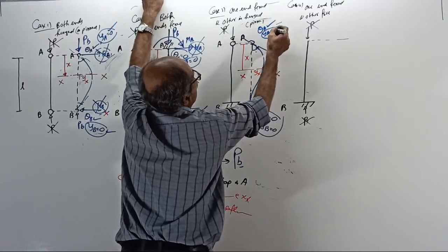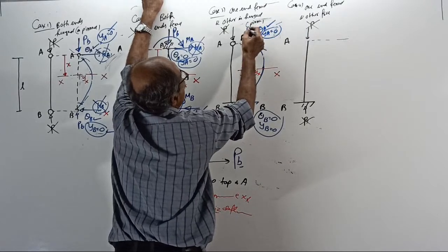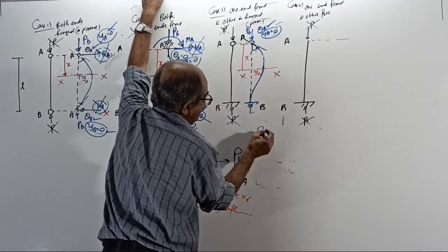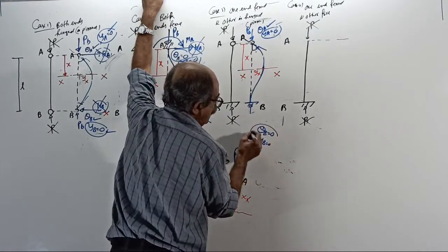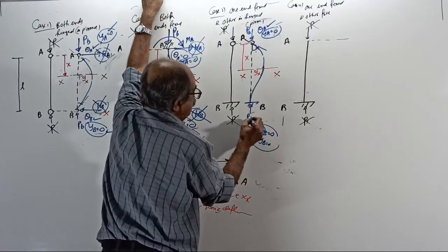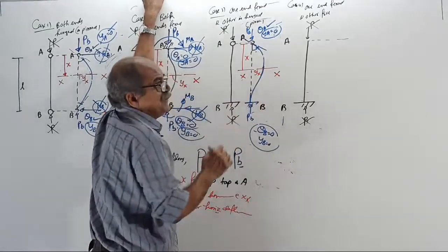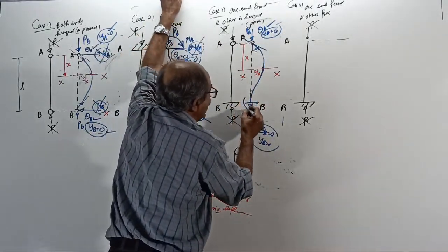So theta A is there, YA equal to 0 is a boundary. Okay. Now tell me, this is the buckling load PB. Theta B 0, YB 0, boundary. Now tell me, at the fixed end bottom, there will be slope 0. There will be a reacting moment.